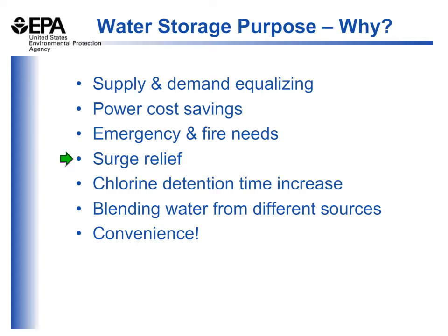and provide surge relief. If you start or stop your pumps on a regular basis as people turn on their faucets or turn them off, you're going to be putting a lot of stress on your system that may result in damage or more wear and tear on your pumps due to increased use or water hammer. And having a water tank mitigates this potential damage threat.